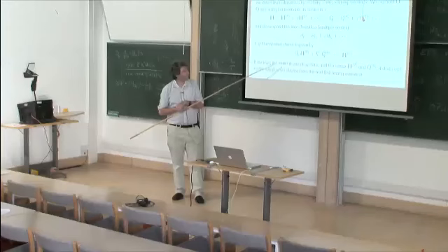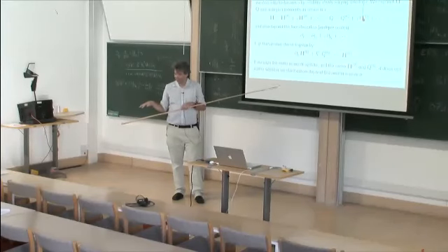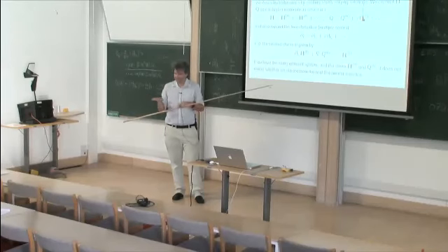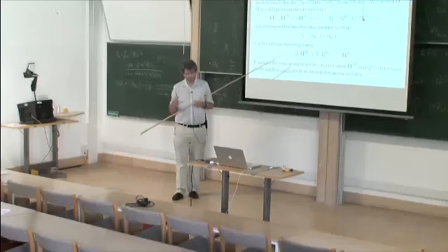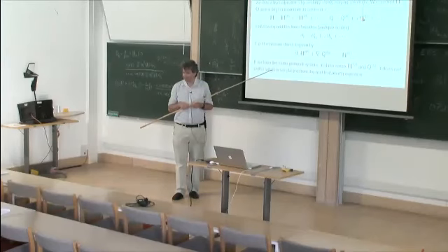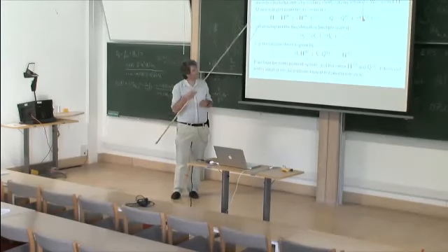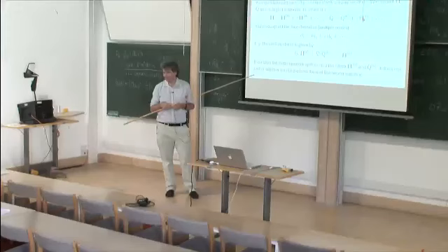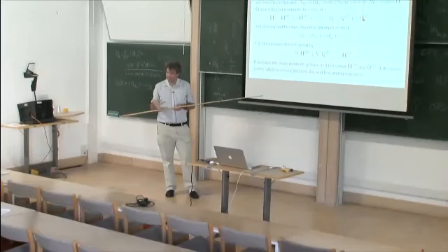Well, when I'm just doing incompressible, then as long as the thermal velocity is big compared to the fluid velocity, I don't care. What you tend to do is rescale the fluid velocity. So you're doing order Mach number perturbations around an isotropic sort of Maxwell-Boltzmann equivalent. The whole story for doing honest thermal flows at order 1 Mach number is rather less well developed. All the obvious things which would give you compressible Navier-Stokes-Fourier when you do the Chapman-Enskog expansion are not very stable.